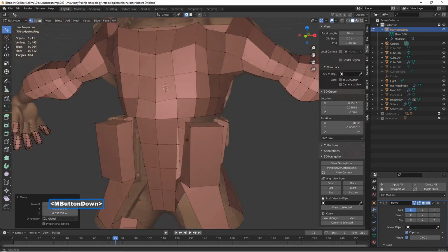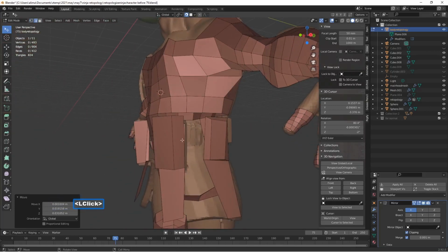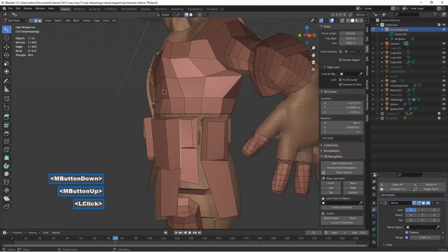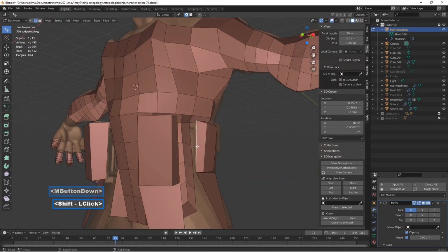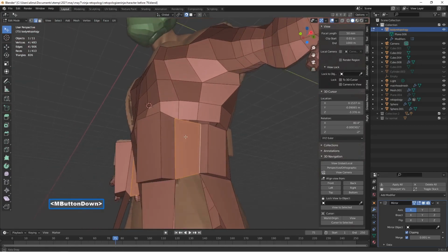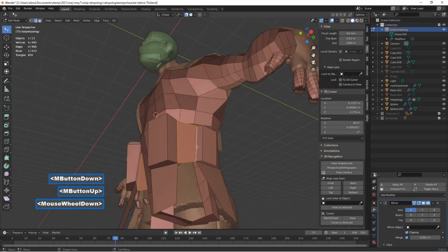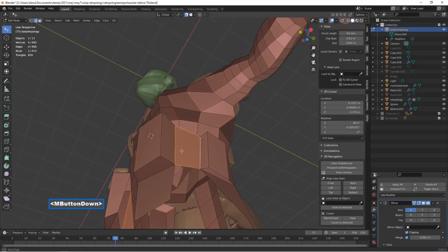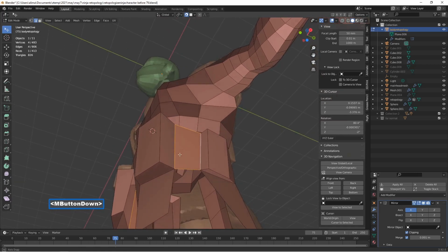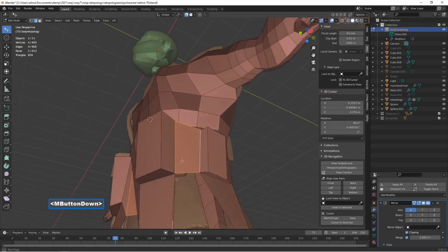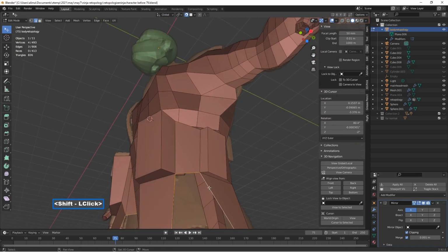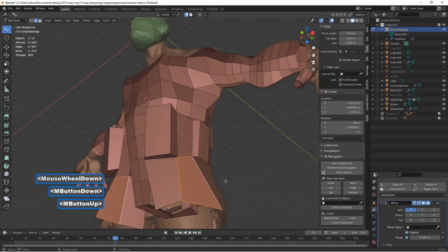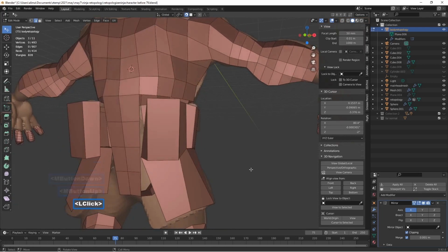Okay, I'm holding the mouse button to take a look. I'm going to select this edge here, select here, hold Shift, select there, press F to link those together. I'm going to select here, as well as here, as well as here, then press F to link that together. I'm going to hold Alt, press A, there we go, to deselect.